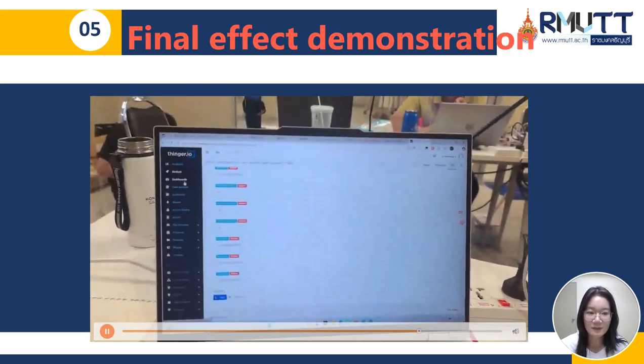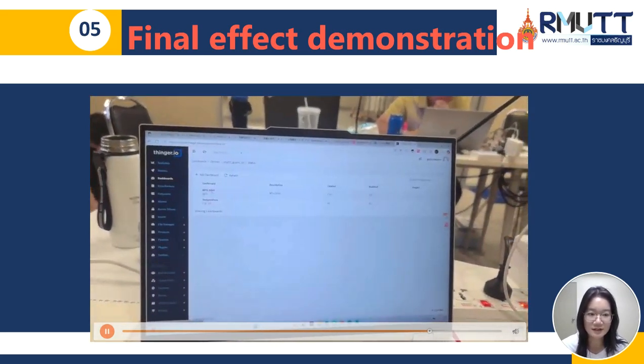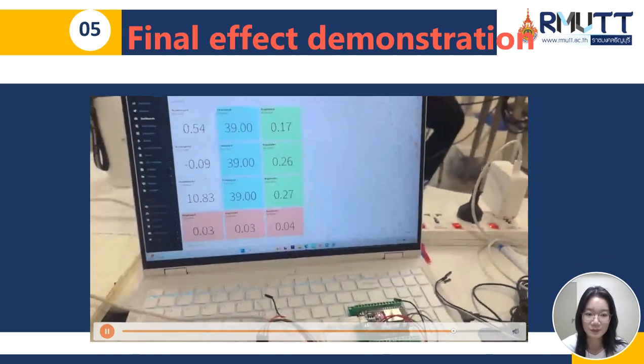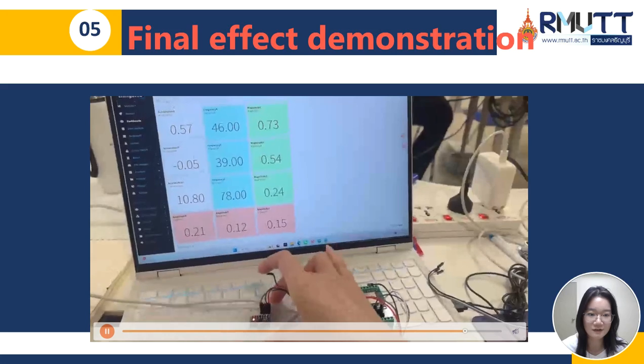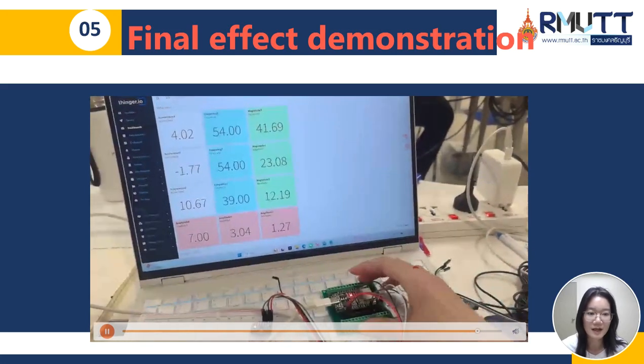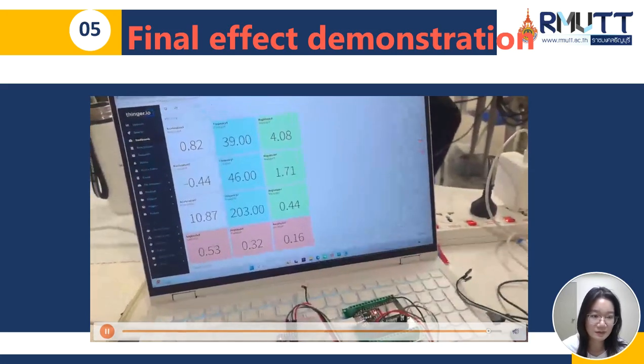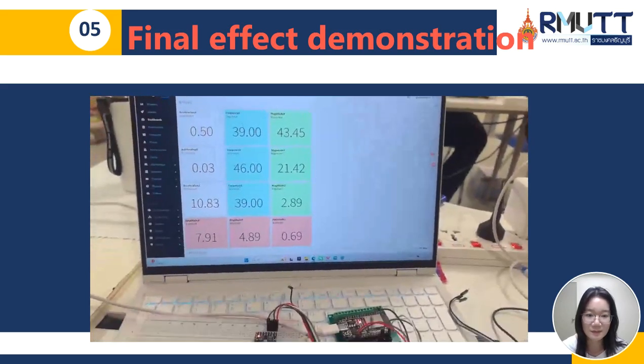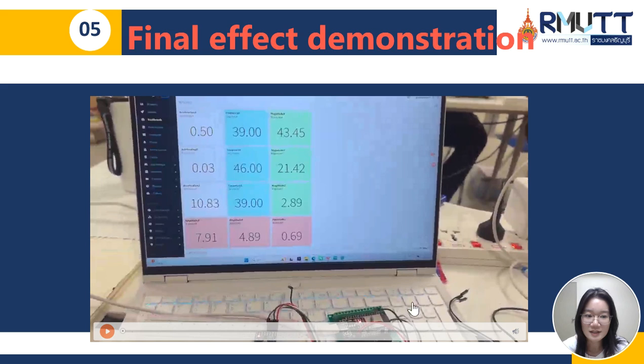An FFT transform is then performed on the data for each axis to calculate the dominant frequency, the predominant frequency of the vibration, magnitude, and the peak-to-peak amplitude. And the data will undergo various changes, and the video shows the validation peak.